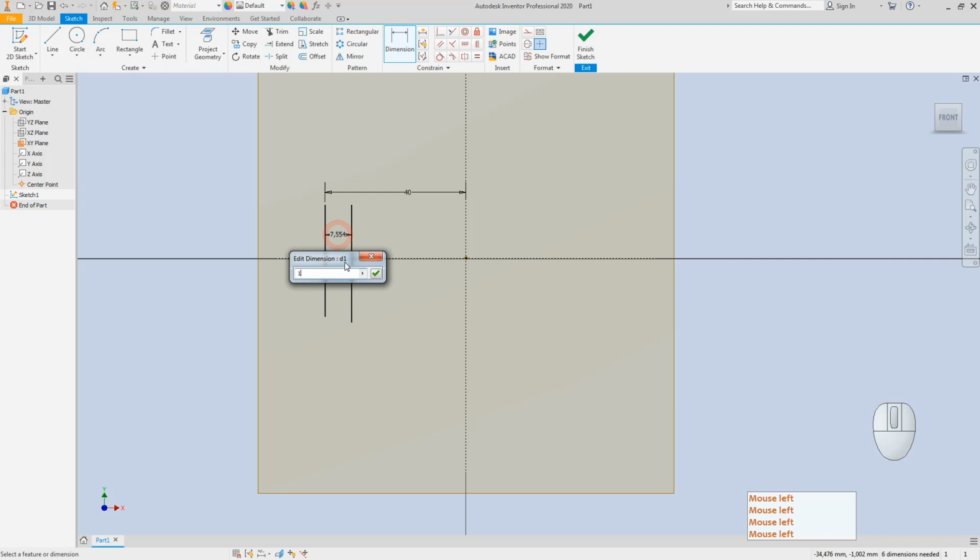In order to create a plane on a point, I will use the sketch points. For this reason, I will just trim the bottom part of the line which I'm going to use for creating the plane purposes. I need those points during the creation of the plane process.